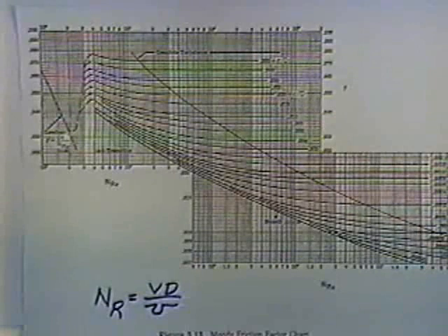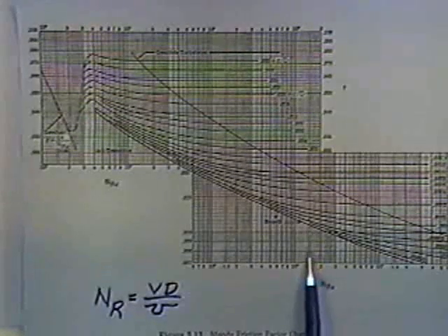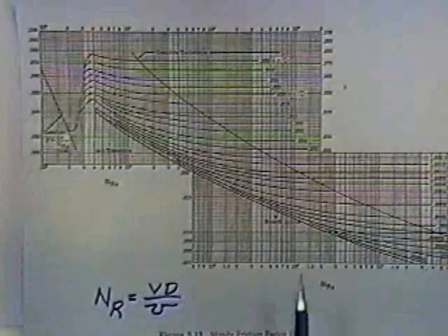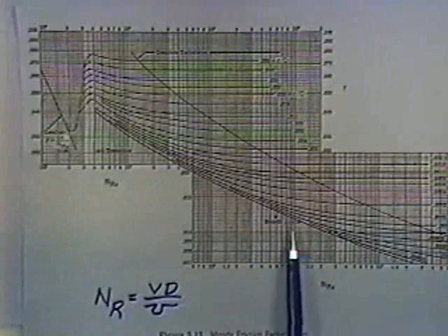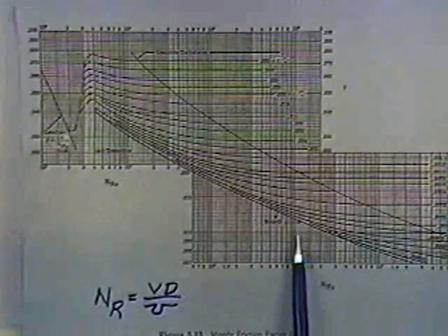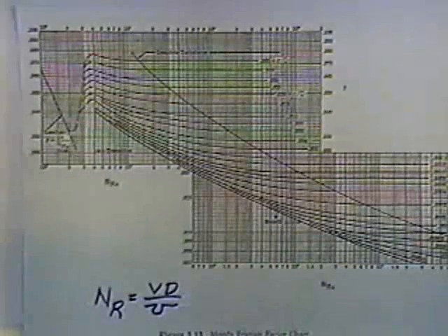And so at the wall of the pipe you have a laminar boundary layer. And smooth pipe means that the boundary layer is thick enough so that it covers up all the little roughnesses in the pipe, so that what the turbulent flow is actually seeing is the boundary layer, not the roughnesses. And so what that means is if you find yourself below the smooth pipe curve, you still just use the smooth pipe curve, that all the roughnesses are covered up by the laminar boundary layer anyway, and so the friction factor is not a function of the roughness. It's just a function of the Reynolds number.